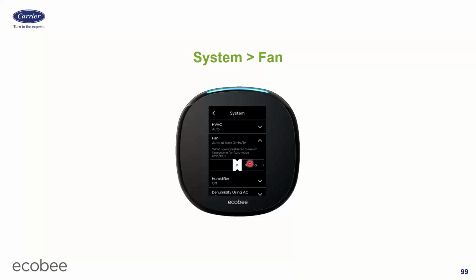I'm going to go ahead and force the fan on now for 9 minutes to make sure I get at least that 15 minutes of fan runtime. And you can set this for anything you want in 5-minute increments from 0 up to 55. You can't set it for 60 minutes. I don't know why. That would solve so many confusion points. If you want to run it 60 minutes out of the hour, you have to basically tell it to run continuous on fan in the schedule. But you can tell it to do any of those.